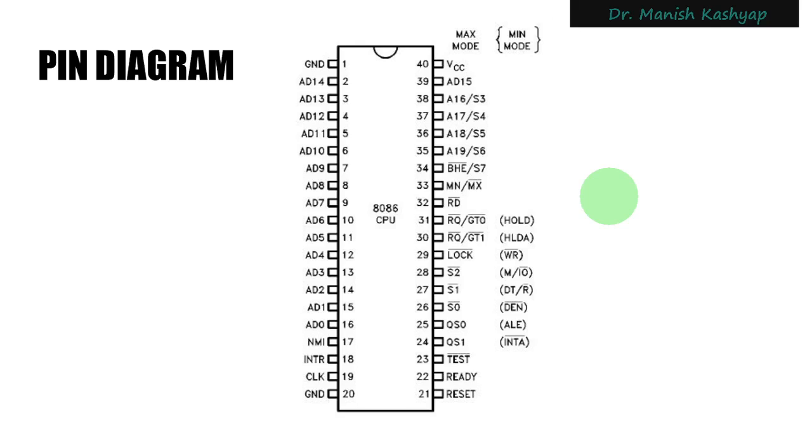Address bus is not frequently used in comparison to the data bus, and we have seen why that is so in the 8085 microprocessor. Because at the beginning of a read or write operation from memory or input output, in the T1 clock cycle only, the address buses will contain the address, and after that, that address might not be required. So from T2, T3, T4 clock cycles, you will have data on these address buses.